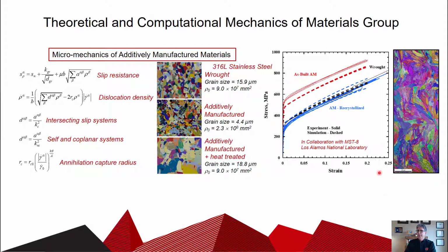So what you see pictured here are what are called stress-strain curves. And strain is a measure of deformation, and stress on the vertical axis is a measure of force required to deform a simple compression cylinder. And so as you increase the deformation, the force required to deform that sample will increase. Okay? And so that's generally the way in which metallic materials will behave. So another very interesting topic area.